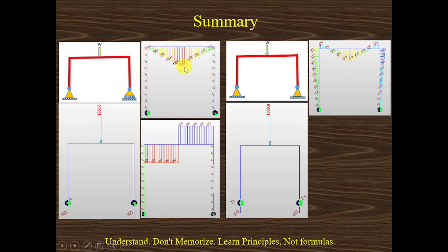So what it is telling is that because of these two different conditions, the moments are now redistributed. The sum of moments is the same: 0 plus 1250 is 1250, and here 375 plus 875 is the same 1250. The only difference is that this will be more economical because our moments get reduced. So in the detailing, we have to provide less here compared to here. Here there will be less reinforcement, and here we have to put some additional reinforcement. Basically, this is the concept of redistribution.